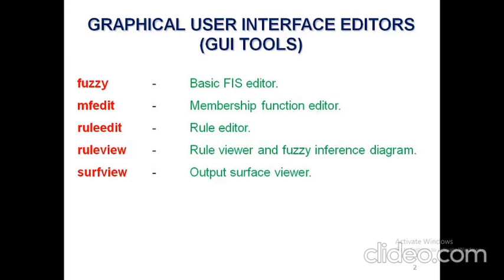If you enter the fuzzy command in the MATLAB command window, you'll get the basic FIS editor, that is the fuzzy inference system editor. MF edit means membership function editor, rule edit means rule editor, rule view means rule viewer, and surf view means output surface. These red color words are commands that you need to enter in the command window to get the respective features in MATLAB.